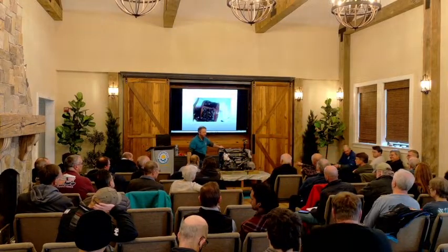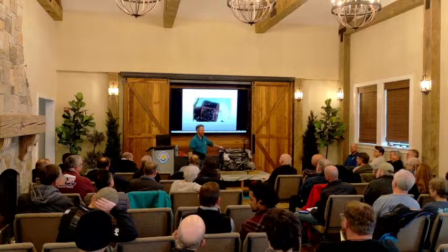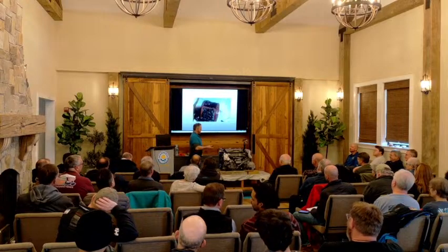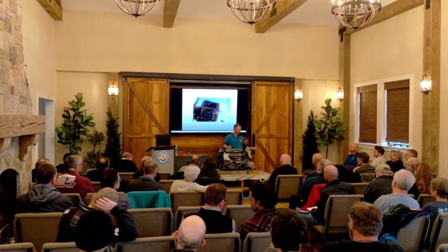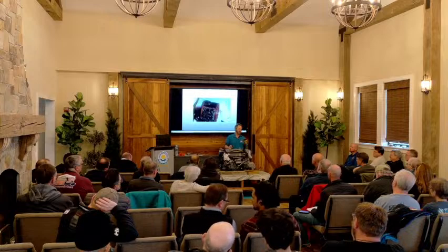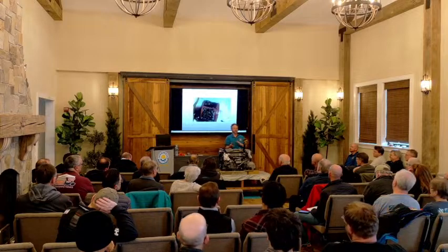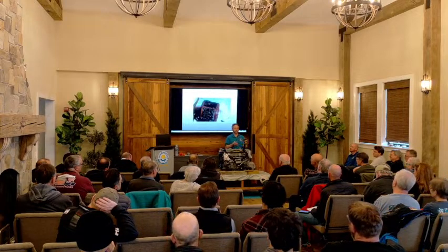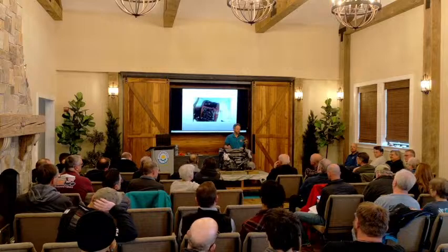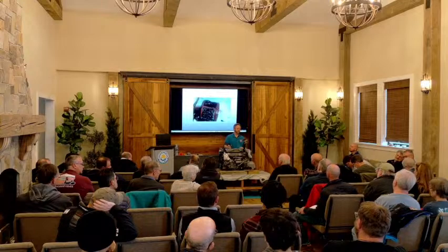Do you have any rules of wisdom on transmissions? Shift at idle? Yeah, so the main thing is only shift them when you're at idle. And the most important thing is the cable adjustment. A lot of times the cable won't be adjusted right, so it's not fully going into forward or reverse, whichever one. And whichever one is not adjusted correctly, that's the one that you end up burning the clutches up or the shift cone. It can also prevent you from shutting the engine down, if you're linked to that. Ask me how I know.